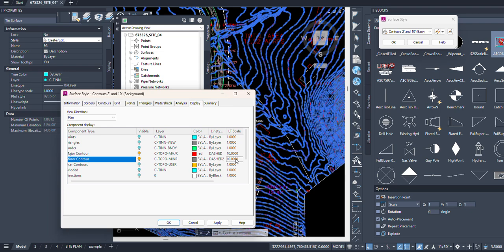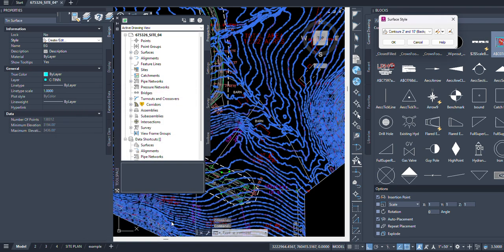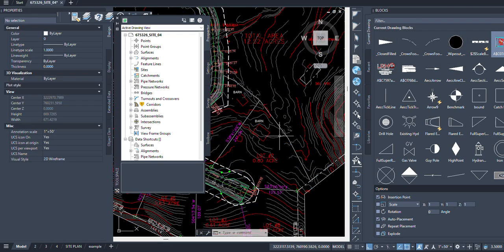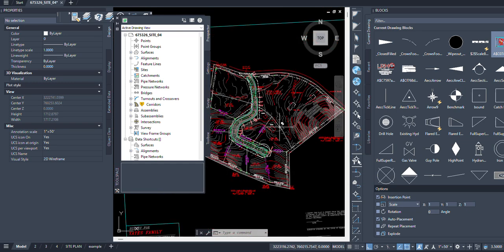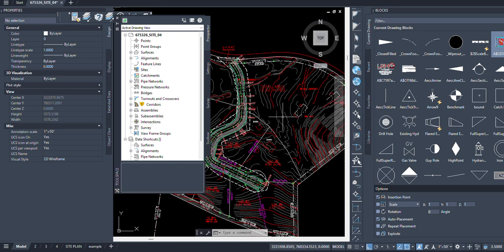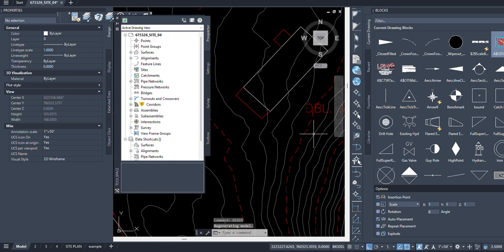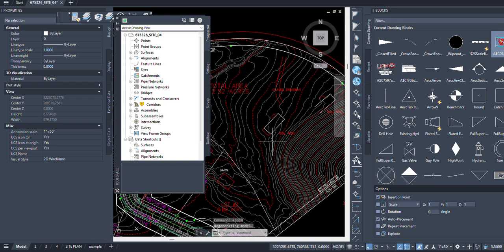If you set the drawing up the way I showed, you don't have to do that. And I just changed that there to show that that gives issue when the drawing's set up correctly. Having those set to 10 actually causes issue. But if we was to turn MSLT scale off and do a regen, then it looks correct. So that's pretty much why that happens.